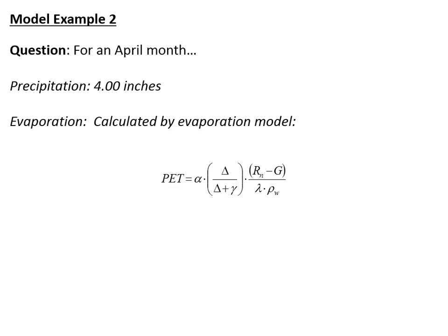If it's a very, very dry month last month, then this month we may not have very much evapotranspiration, simply because there isn't the water available to be lost. If it's already all dried out, then you're not going to have additional evapotranspiration. And so PET, potential evapotranspiration, is a way of characterizing how much evapotranspiration could occur based on the radiation, humidity, temperature, and so on.